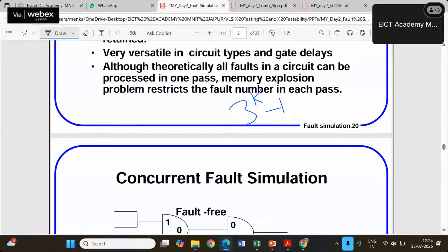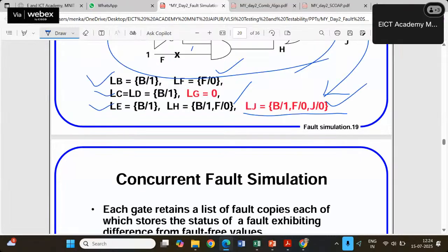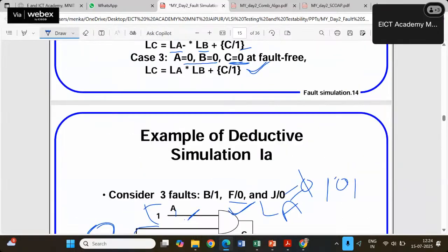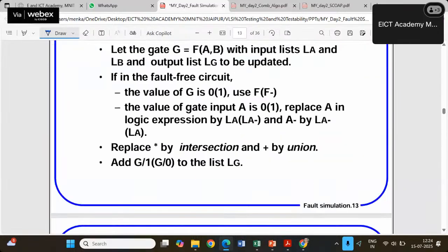Serial fault simulation will not work well for bigger circuits. So the only algorithms which can actually afford multiple fault simulations altogether are the solution. The parallel fault simulation, because it always reserves one fault-free and other faulty spaces, actually requires multiple spaces.